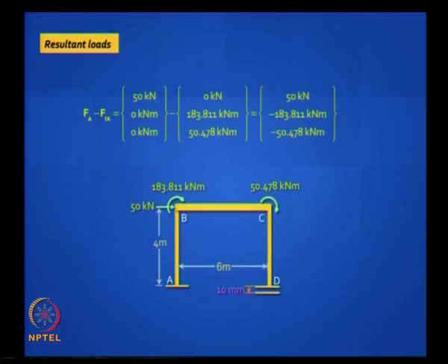And so this is identical to slope deflection method, but you made an assumption. Assumption is axial deformations are negligible. How true that is for this problem we will know shortly. So you have got these moments. So your problem is now reduced to this problem: 3 loads, no vertical loads.